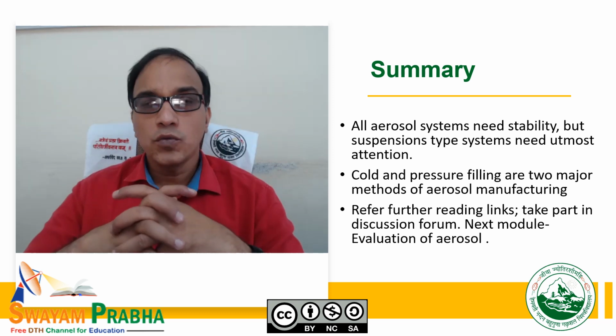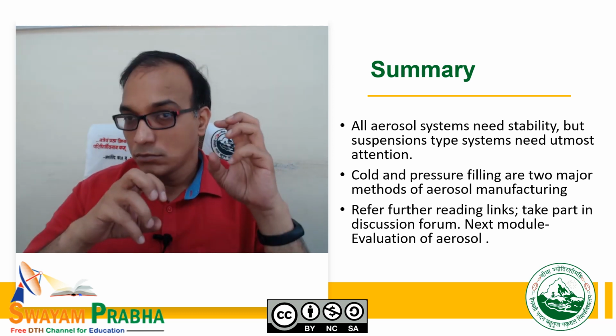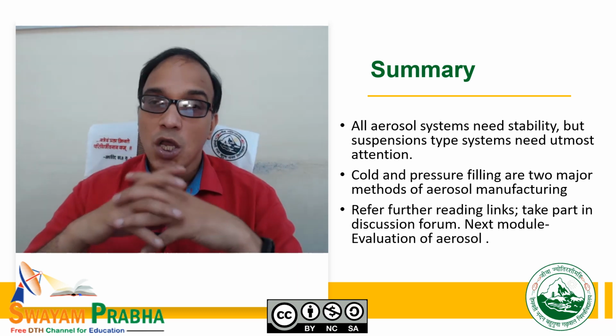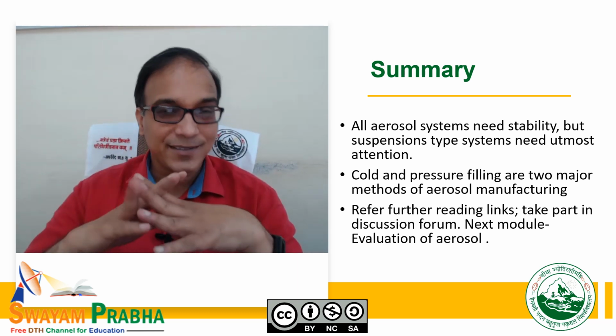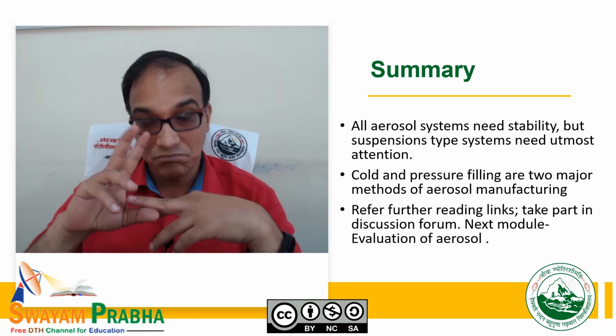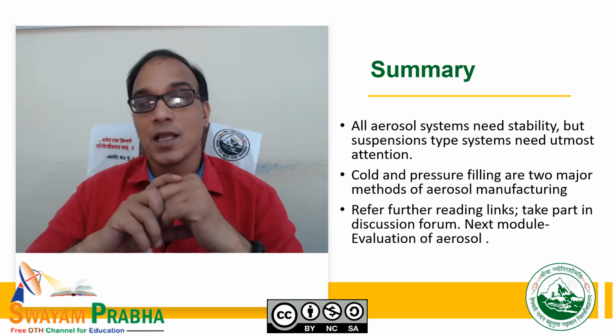Do what you can, whatever parameters you can control for stability of the overall aerosol system. There are two techniques of manufacturing: pressure filling and cold filling. These are the two major methods of aerosol manufacturing.